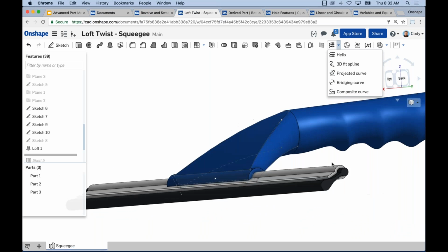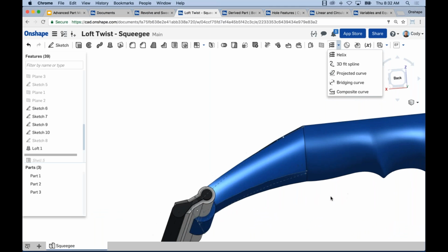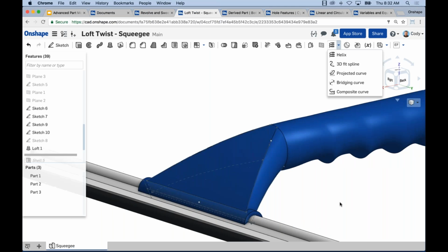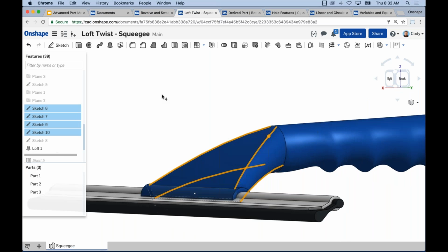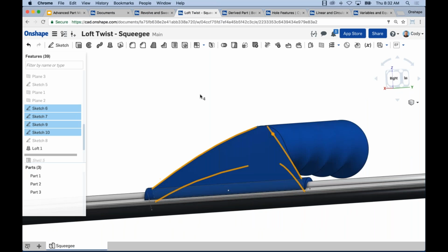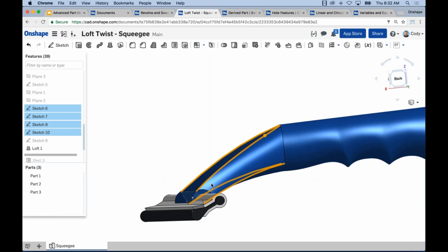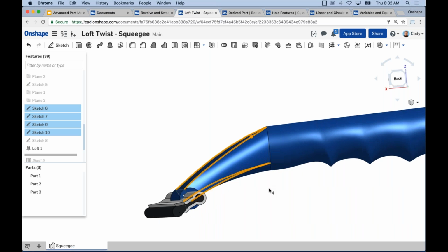And I think the key thing with a loft is you want a smooth transition. More often than not, a smooth transition is very important, and a transition that you control. Now, of course, it's a lot more work to construct. If you look at this, 4 independent sketches with splines on them. So it's going to take more time, but of course, I control what that twist looks like, what the transition looks like, and it's very easy for me to manipulate it.